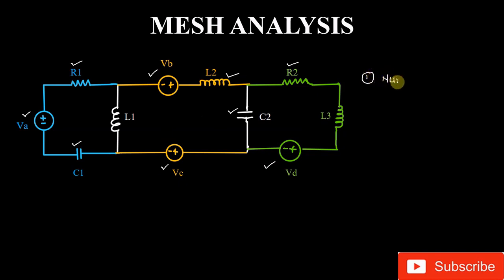The number of meshes in the circuit. How many meshes are there, that we can find out. As I told you, a mesh is nothing but a closed path. So if you see this diagram, this will be mesh 1, because if the current starts from the positive terminal of the battery, it goes to R1, then L1 and C1, and it is closed. The path which originates and terminates at the same point is called a loop, and a loop is nothing but a mesh. So this is my first mesh or first loop.